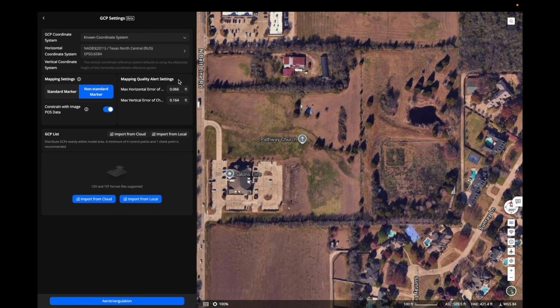If the final checkpoint error exceeds the selected threshold, I would treat that as a signal to review the coordinate system, vertical height reference, elevation units, GCP checkpoint setup, and GCP image marks before relying on the final output. After confirming these settings, I'll import the GCP file.